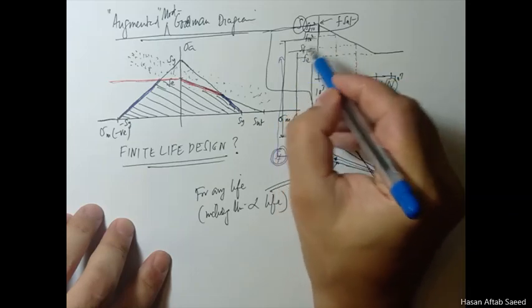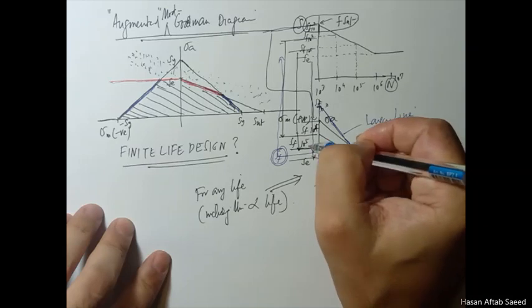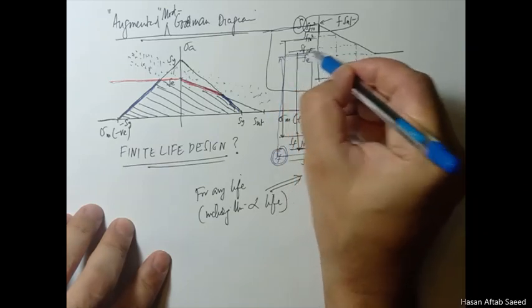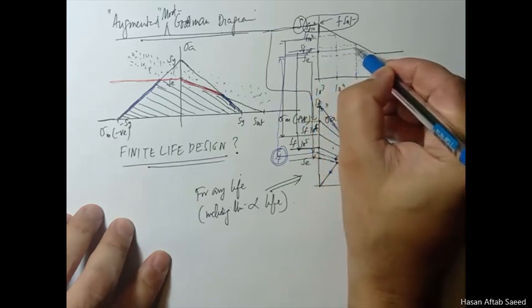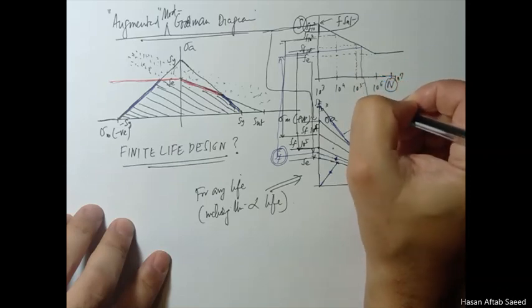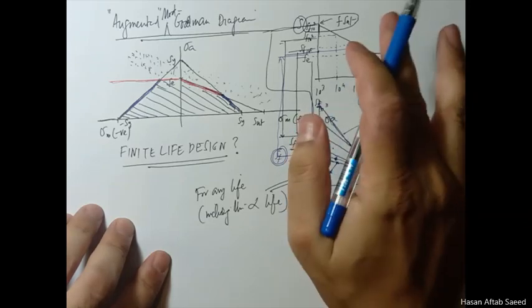Then you plot that SF, because this SF is somewhere between SE and SF10.5, somewhere around here, wherever that is, you plot it there, and then this is your point, and then you go along to this point, and this is your number of cycles that it will withstand. So you can use it in the reverse direction also.